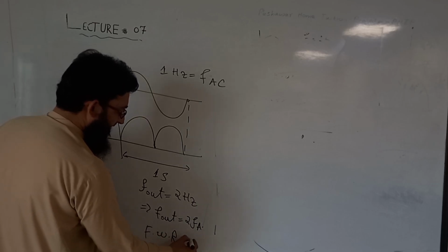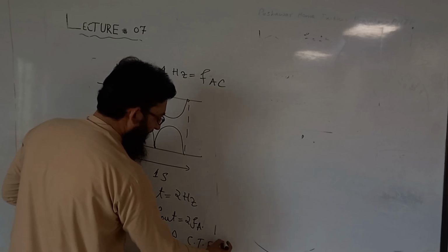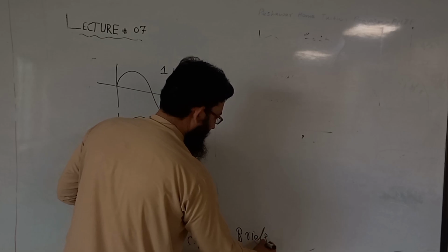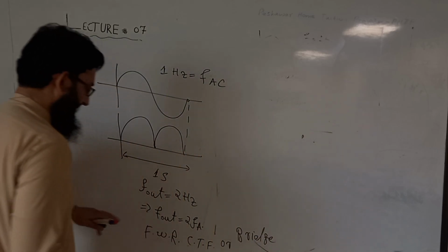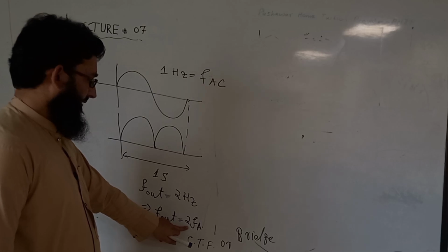Either it is a center tapped full wave rectifier or a bridge, in both cases the frequency out will be equal to 2 times the frequency.